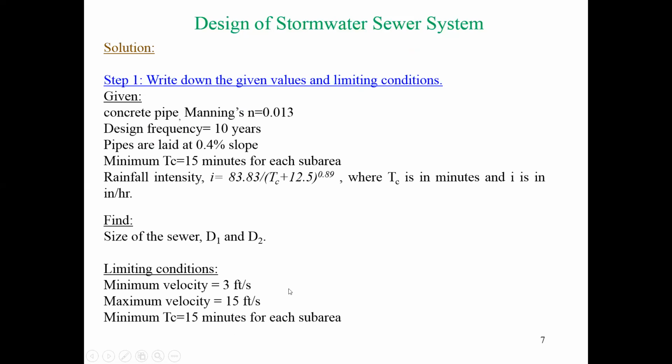That's because for some counties, they fix the minimum time of concentration so that in calculation, engineers don't get too much peak runoff, because that is sometimes a misleading value. So that's why they fix a minimum time of concentration for each area. So for this area, the minimum time of concentration is 15 minutes.